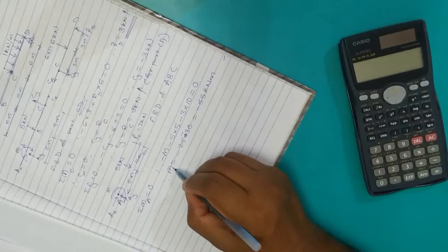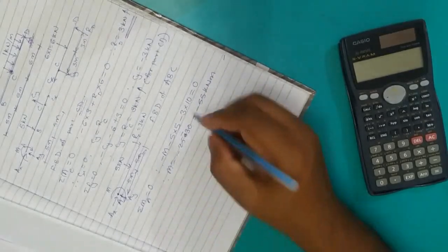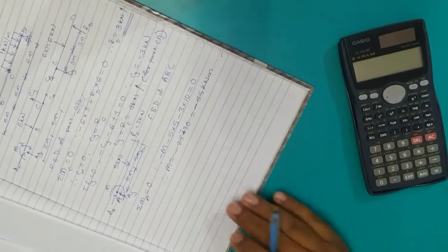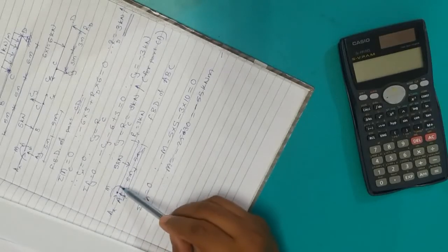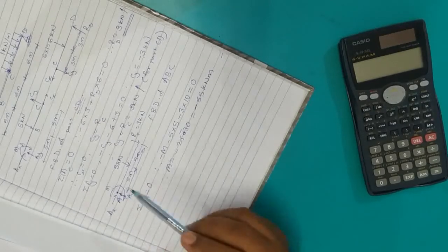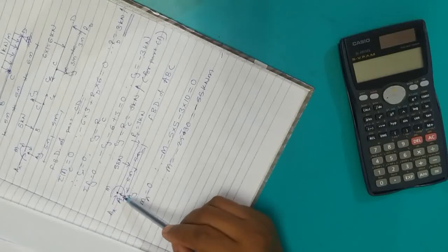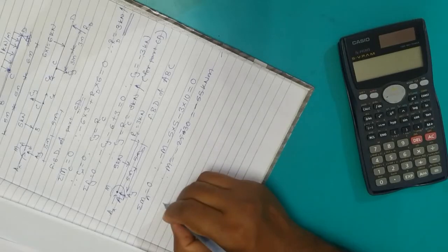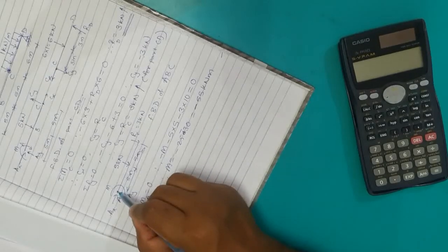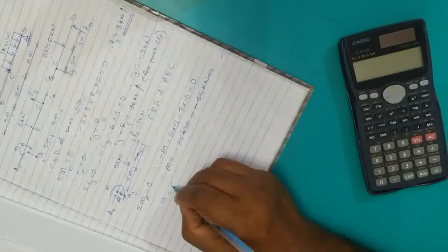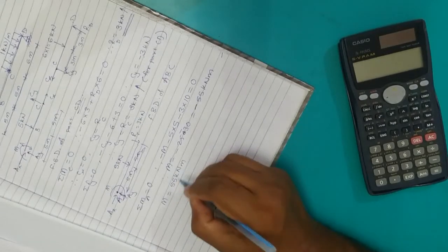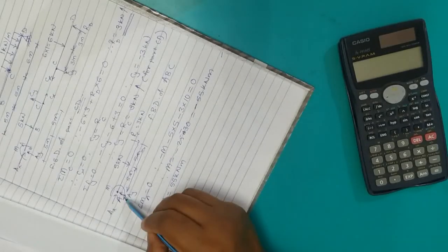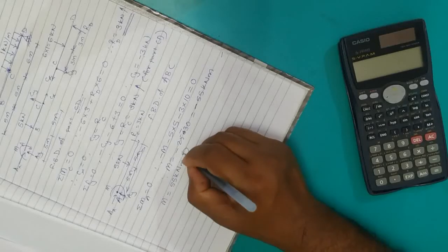Remember, you have calculated moment, it has to be in kilonewton meter, but now we have calculated it with a minus sign. What exactly is this minus sign representing then? Our assumption for the rotational sense of this moment has gone wrong, so that's why we are getting a minus sign over here. So let's correct the moment which is present for the fixed support of A as 55 kilonewton meter. Let's remove that minus sign and now correct the rotational sense. Our assumed rotational sense here is clockwise. Let's make it anti-clockwise.